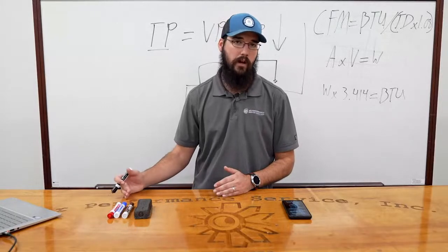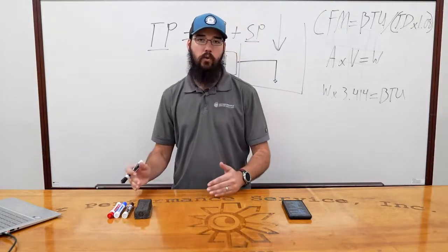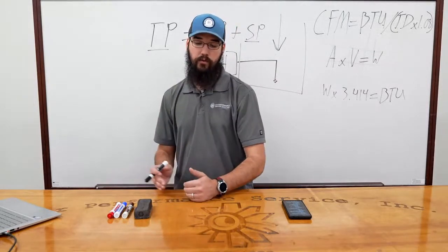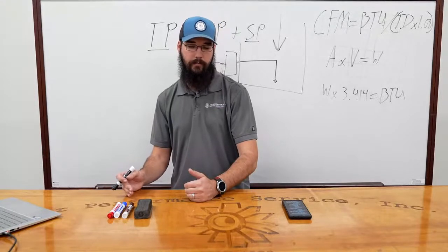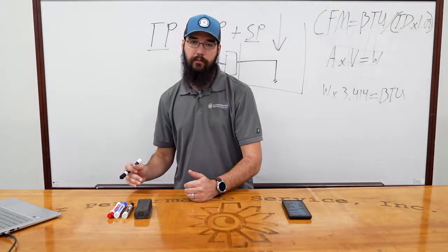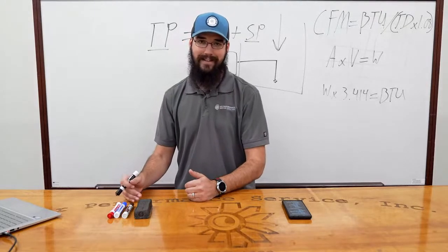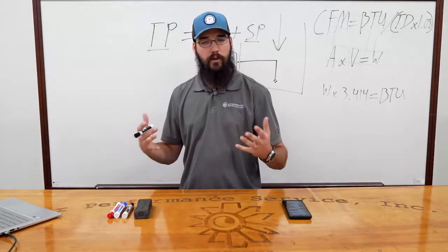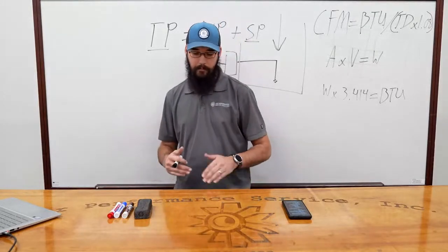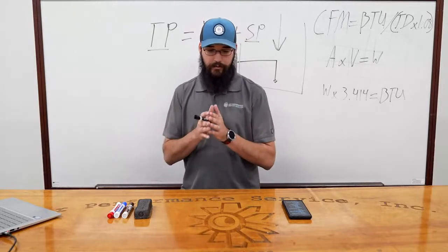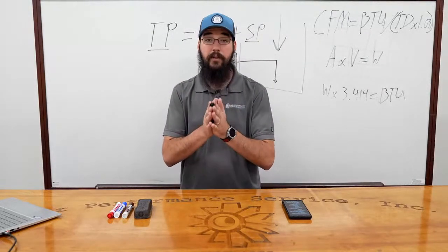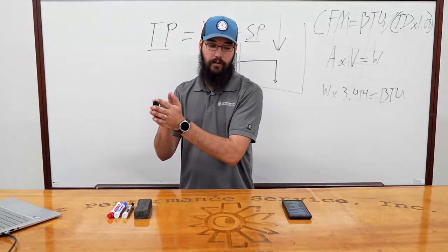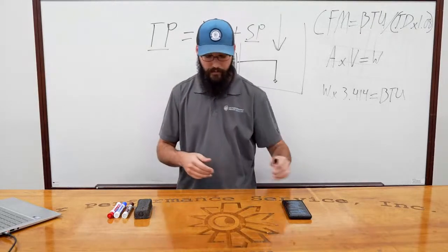Why is the superheat so high? You may not always correlate that the superheat and saturation are high together. If you're honing in on just the superheat side of it, that would be a really easy road to end up diagnosing a bad TXV. And we all get into blaming metering valves all the time. They've got that whole genre to it, but that's something you have to be careful with. So both of those elevated together are going to cause a symptom like that, basically, is my point.